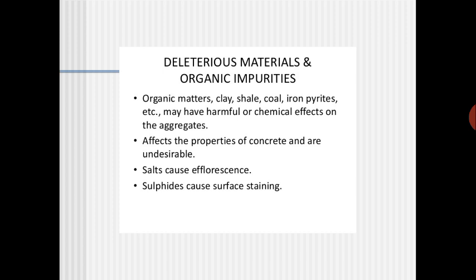And of course these are all undesirable. Of course, these deleterious materials, I already said, are the salts and the sulfides or the sulfates present in the aggregates, and I already explained this with respect to the chloride attack and the sulfate attack on the concrete. And of course this chloride and sulfate attack is nowadays common, and that has to be studied properly.